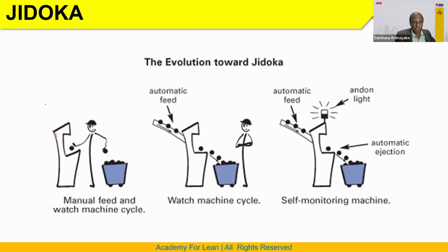This is manual feeding. Normally, the person feeds, does some operation, and takes it down. Then automatic feeding happens; if any defect comes, the machine takes it out, and a person needs to check. With error-proofing, the machine feeds, and if there is an error, there is an alarm, a beep beep sound and a color signal saying there is an error, please come and check.